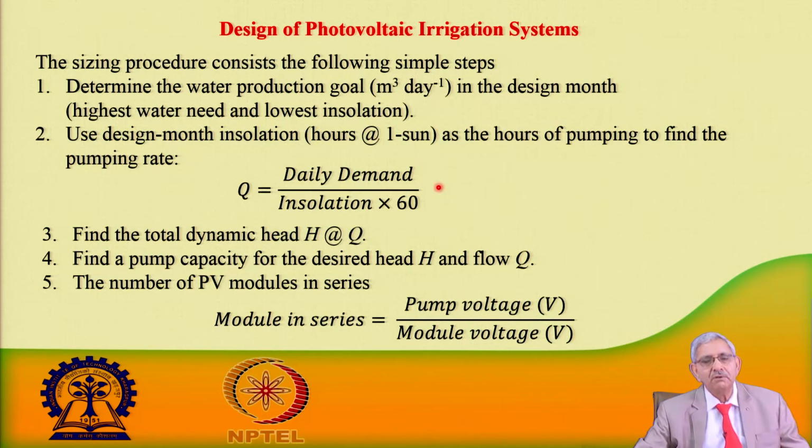We studied the water requirement of crops in the previous lectures, if you remember, how to estimate the evapotranspiration requirement of the crop using the different methods I discussed. The pan evaporation method is one method, but here the highest water need is taken. Suppose we have a perennial crop, or a crop to be grown during the summer months. The water requirement during the summer, the peak period, has to be taken into consideration.